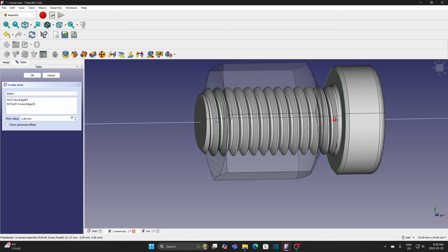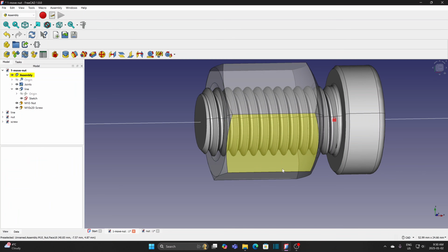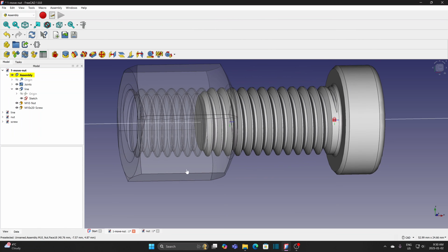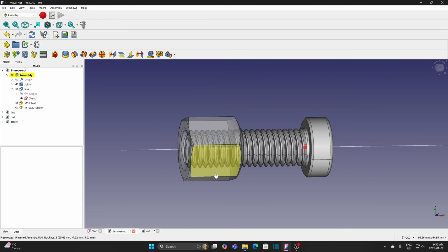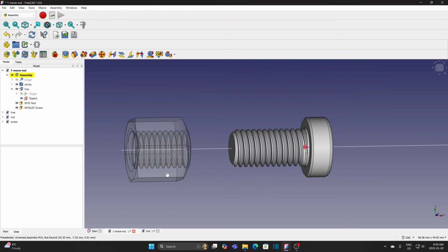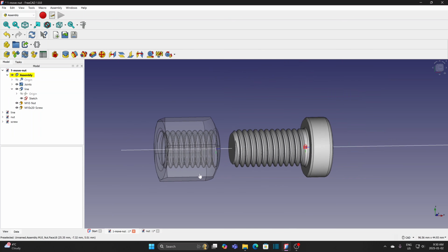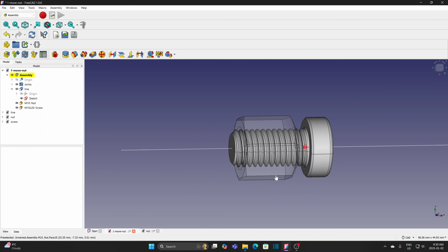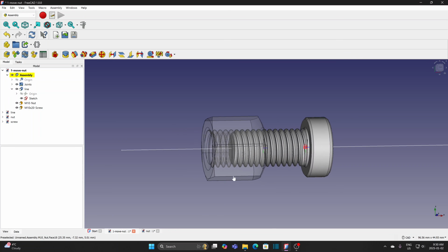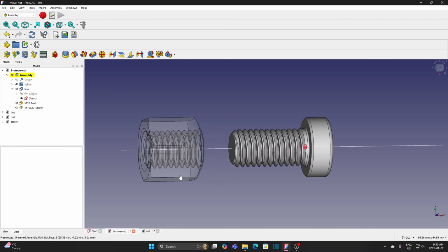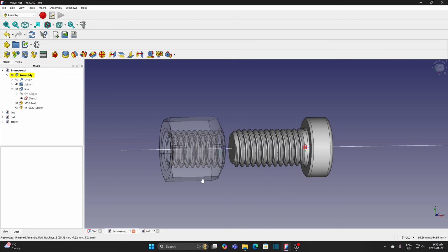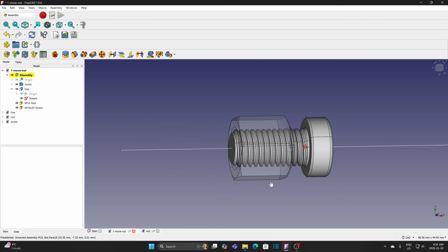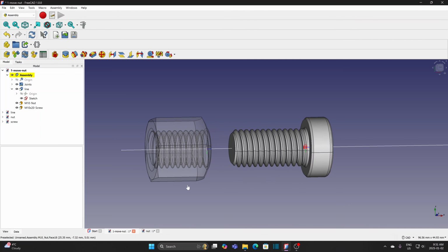Pitch radius is in fact the pitch of the screw. 1.5 mm for M10 screw. The joint is created. Move the nut will rotate the screw. The rotation direction is correct. The screw joint is completed. It is similar in the example linear actuator I created before. Instead of moving the nut to rotate the screw, I will try to move and rotate the screw at the same time and keep the nut fixed. Let's move to the next example.